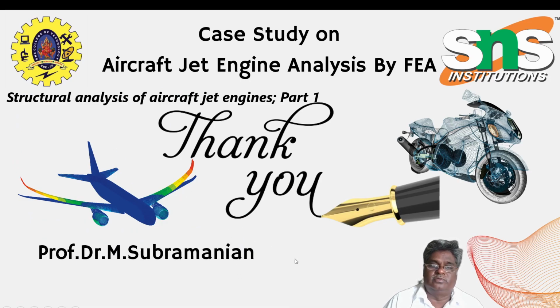In this video, we have seen a summary of aircraft jet engine analysis by finite element methods. First, we identify the aircraft jet engine component geometrical shape, profile, and aerofoil, creating the geometrical shape by using CAD software. Then the discretization approach, meshing, then material properties, assigning the boundary conditions, and then we discussed various structural analyses of aircraft jet engines in part 1.